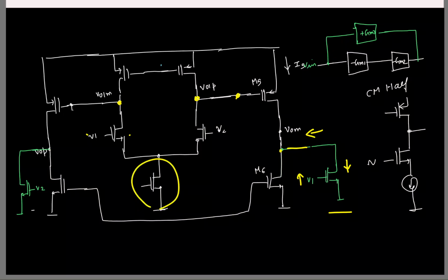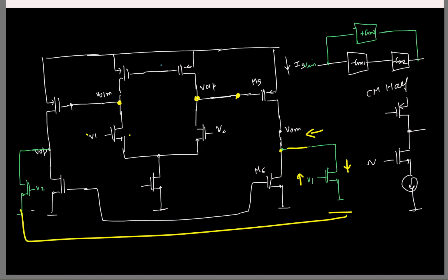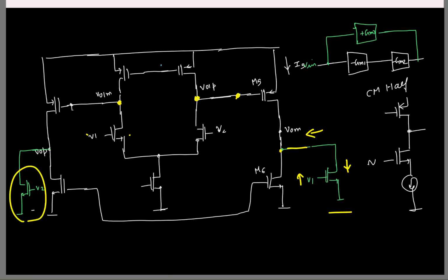So what do you suggest now for GM3? I mean, instead of having two transistors like this, what can I do? Apply the same configuration of the below of the OTA. Like connect the sources and so I can put like this and fix its current here. Is that fine? I mean, basically, the way I have drawn it here, these are pseudo differential GMs, right? Without any common mode rejection. The moment I add a current source fixing its current, we get a common mode rejection, right? So that's what we'll have to do.